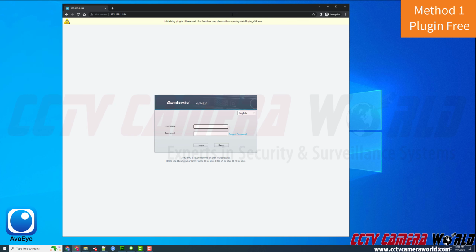and hit enter. It should open up this web page where you'll see the login screen for your NVR. On the top, it'll ask you to install a plugin. If you do not want to install a plugin because you're restricted by your corporate environment or for any other reason, you don't have to. Type in the username and password for your NVR.